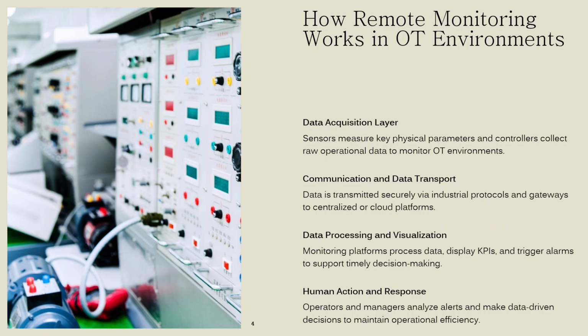These sensors are connected to controllers like PLC, RTU, or DCS controllers, which execute control logic and collect raw operational data. The next layer is communication and data transport. Industrial protocols such as Modbus, Profibus, Profinet, DNP3, OPC UA, and MQTT are used to move data from controller to